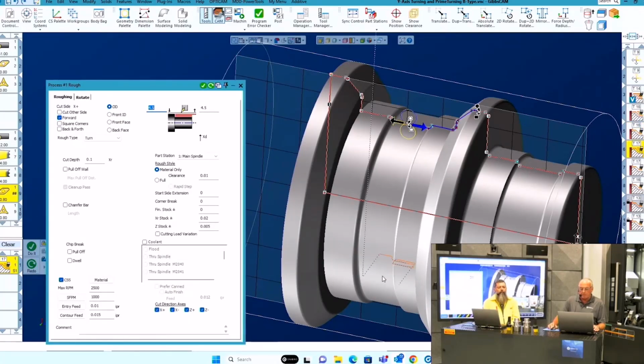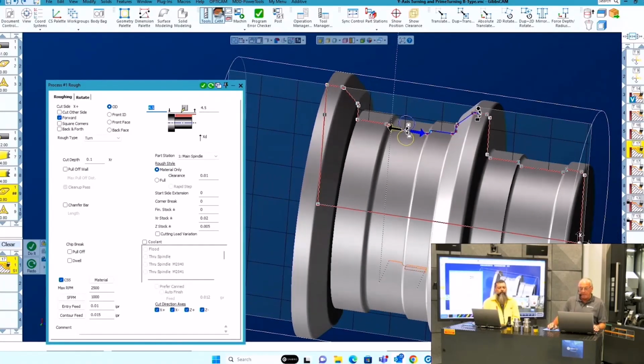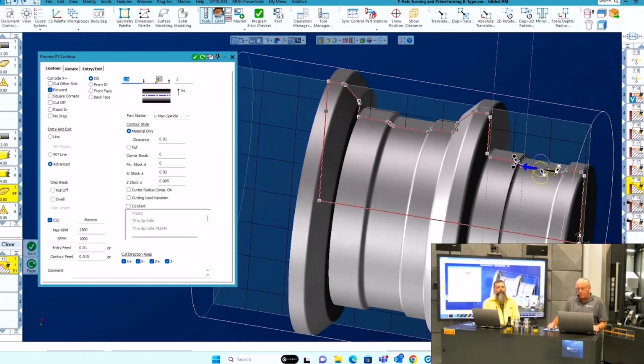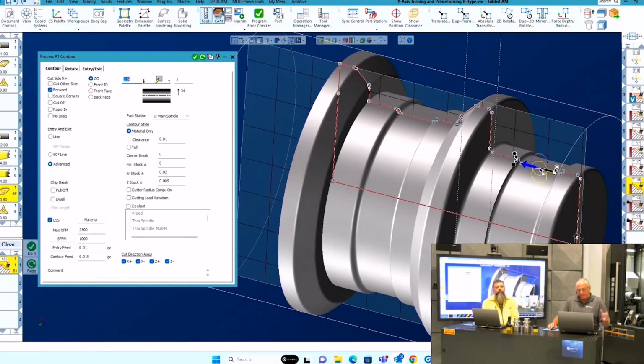We're going to do the same thing over here in the little white groove down there, and we flip it around over. We are using now tool number 17, which is pointing in the other direction over to that shoulder over here, and you will see that later when we do the simulation. Again, cleaning up with material only set, only gives me toolpaths where material still exists. And we do the same thing over on the front here, and one more time. Flip the tool around, another 30 degrees or something like that, and machine that area again with material only set.